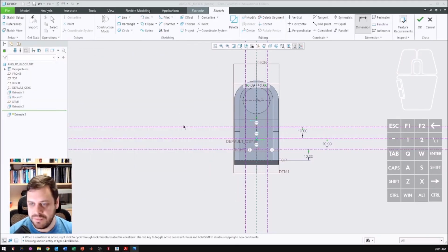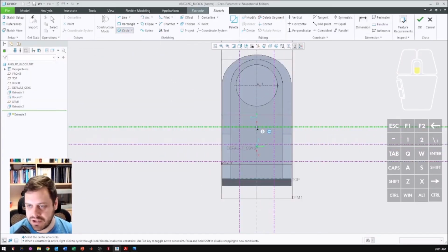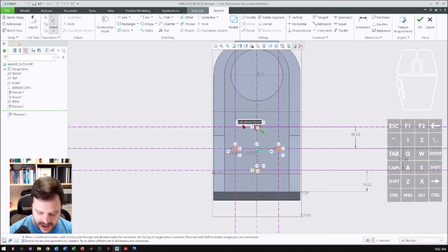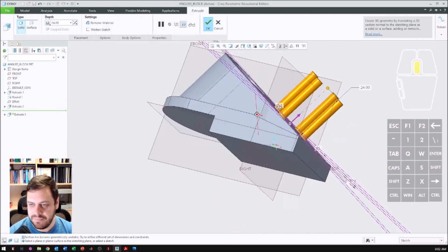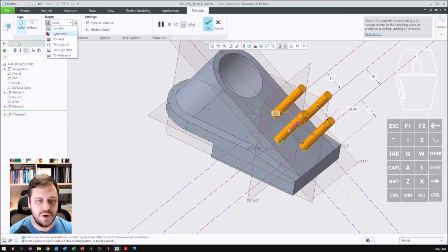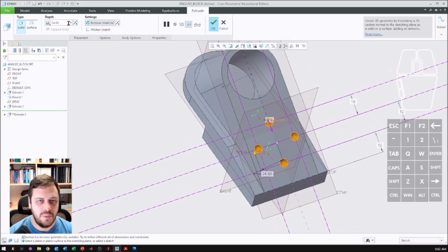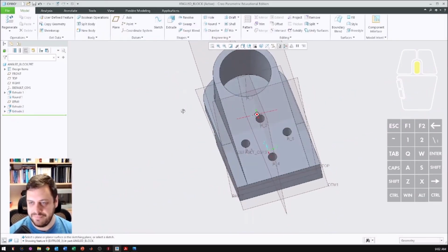Why this becomes important is I can do the actual geometry I want to extrude super quickly. So if I pick those 4 locations that we want and make sure they're all equal to each other and center, click out, and then make that 4 millimeters, then go OK. I can now use my depth tool, and you can either click the little purple arrow you can see on the screen through here, or just simply click this one. So it'll basically eat away material. I want those to be 10 millimeters in depth, and go OK, and you're done.